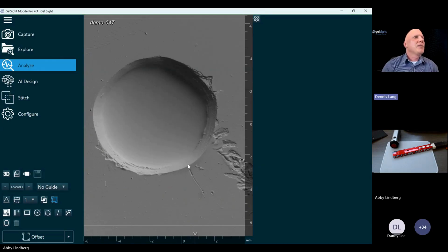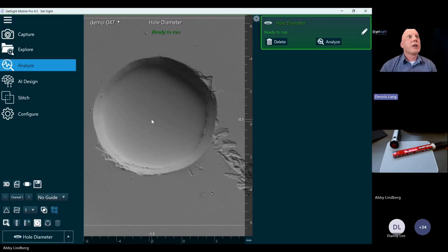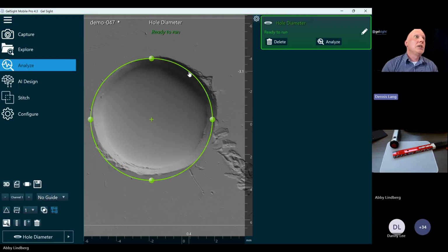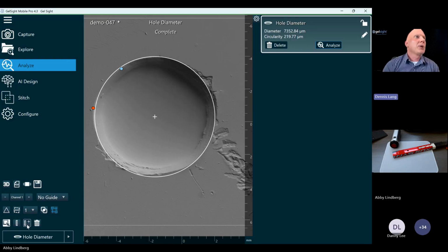But then once the bit dug in and drilled the hole, you can see a couple of different things that are very typical of composite holes, even in highly sensitive areas and applications. And that is you start to see chipping around the edge where you either have some delamination between the fibers and the resin. You can chip that resin at the surface. It's often a very brittle material or somewhat brittle material. Then it fractures like that.